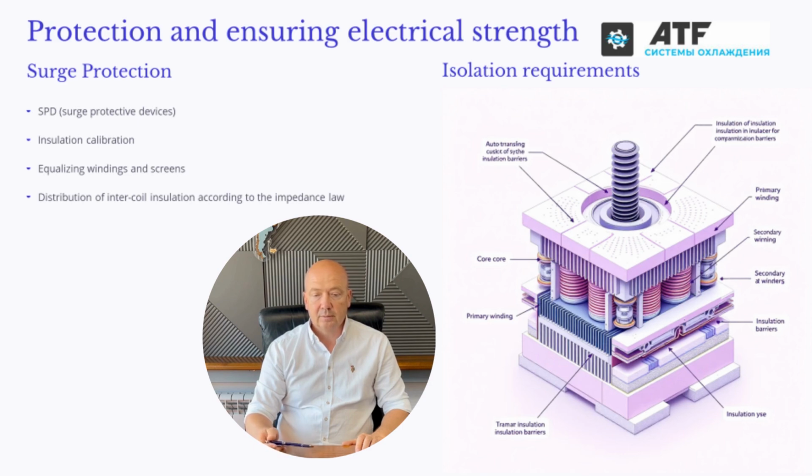Electrical strength. The insulation between windings must be designed to withstand both the operating voltage and the emergency voltage. Special attention must be paid to the regulating winding, which is subject to differential voltage, and the switching equipment, which must withstand sudden voltage spikes.